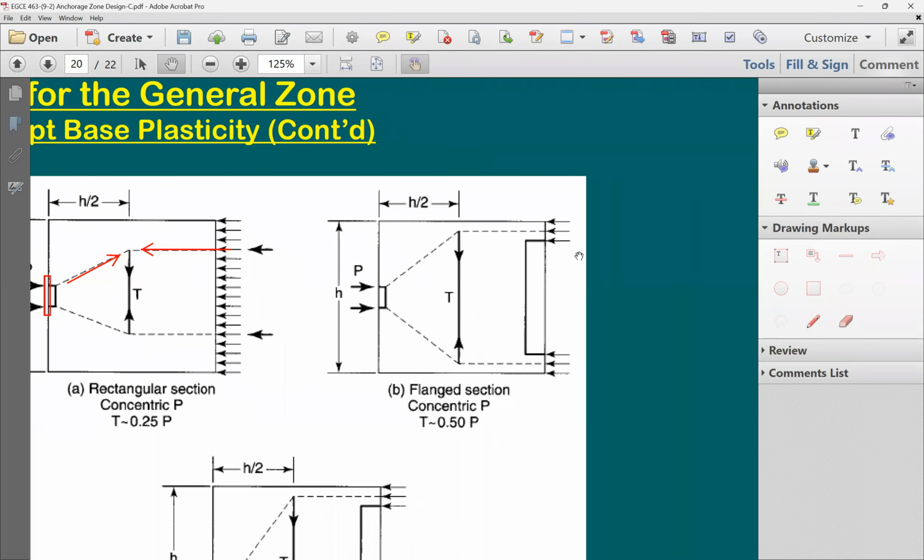Unless you have a beam that is completely solid at the end block, and right after this, it's going to look like an I shape. When you have an I shape like this, it means that you are pushing and controlling the force on the top to be in the flange, and most of the force also to be in the flange. There's going to be some little bit of a force in the web. This is going to be here the beam web, but most of the force is going to be on the flange. So here you're controlling the location of the force, you just push the top.